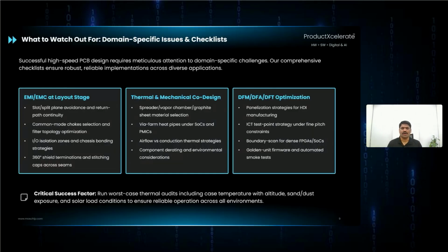Let's discuss how MosChip deals with domain-specific issues and the kind of checklist we follow. Every vertical has its traps. We shall now quickly discuss a few of the domain-specific pitfalls. Automotive gateways fail EMI/EMC if PDN noise is not in control. Industrial gateways suffer connector and component failures under thermal stress over a period of time. Wearable gadgets run out of battery because burst overload or workloads weren't profiled well.